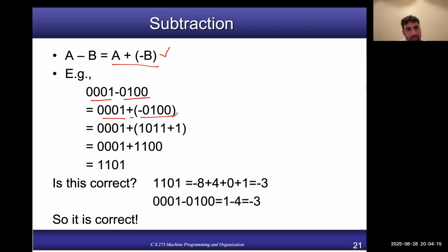In digital hardware, as I explained in the previous lecture, negative numbers are represented by finding the twos complement of the number. So if I want to find the twos complement of this binary number, first I find its ones complement. I toggle all its bits, so it becomes 1 0 1, and then I add 1 to it, and it becomes 1 1 0.